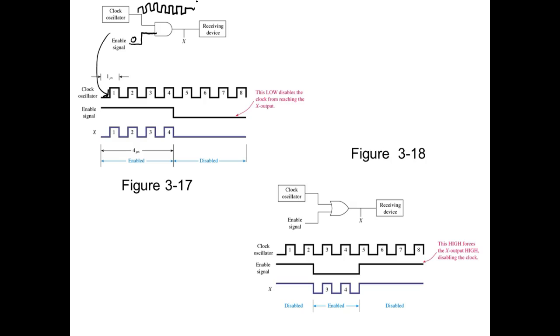Can't say nothing. A nothing is a nothing. We're going to get a low out. That's the big difference. In digital, there's a big difference with a nothing. A nothing we call a float. A float means it's going to be some voltage, but it's going to be inside that illegal range there, and we call that a float. And that's what we consider to be a nothing.